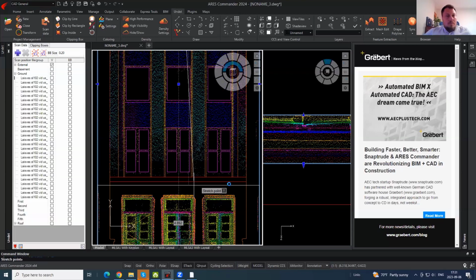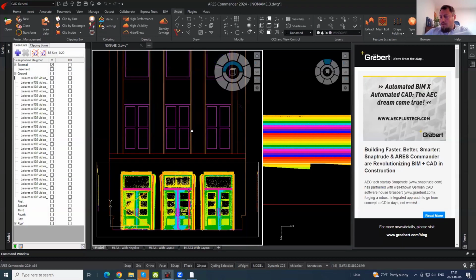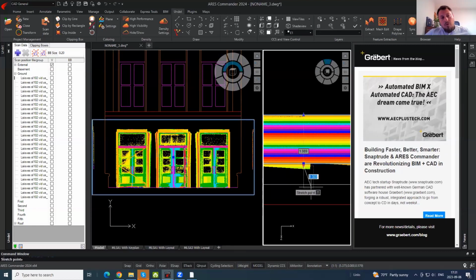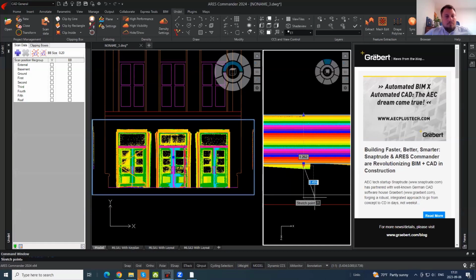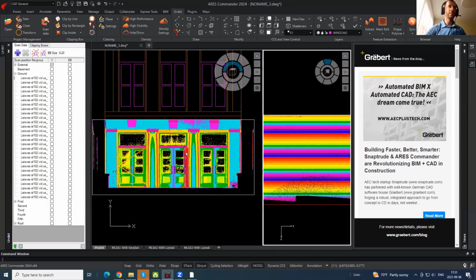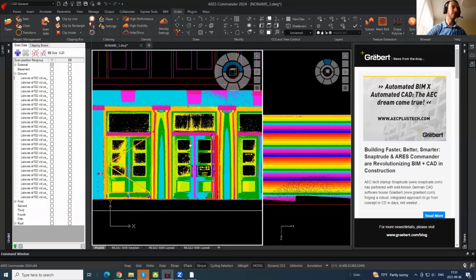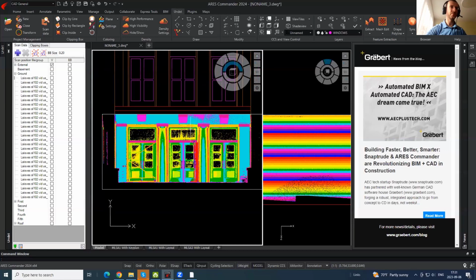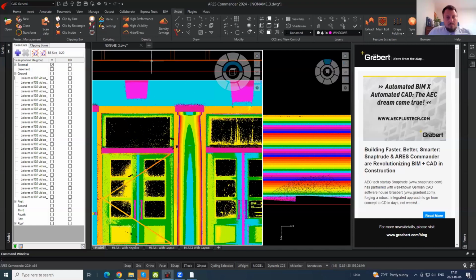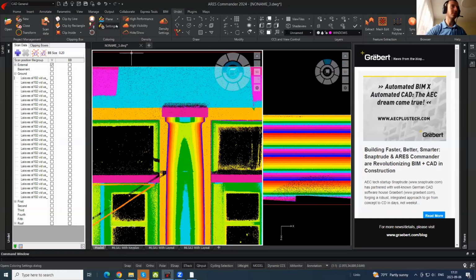And there's one question. Why are you using coloring by plane mode? Because we have coloring by intensity, by true colors, black and white. But why use coloring by plane? It's to understand faster where the plane is changing. For example, here we can see pink, blue, orange.